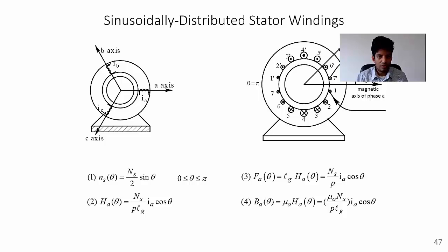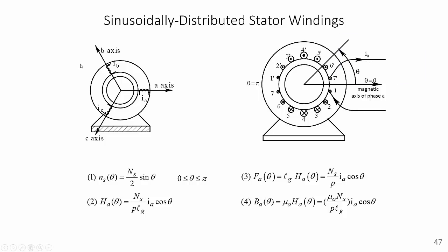To overcome this issue, in an AC motor, the stator consists of multi-phase windings which are spatially distributed. As seen in the slide, for the case of a three-phase system, the A-phase winding, B-phase winding, and C-phase winding are spatially separated by an angle of 120 degrees. In addition, the density of each of the three-phase windings is sinusoidally distributed. This ensures that a balanced three-phase sinusoidal current induces a spatially distributed flux with a constant magnitude that rotates in time with a frequency determined by the frequency of the input current as well as the number of motor pole pairs. The image on the right shows the winding distribution for a single phase, namely the A phase.